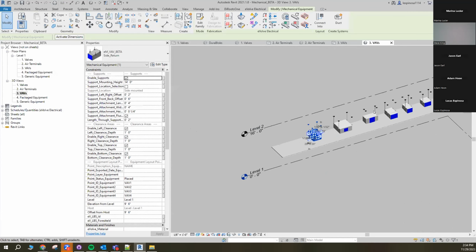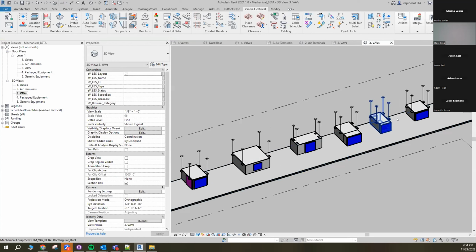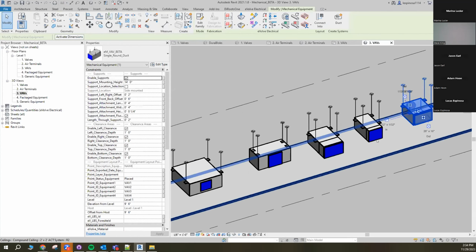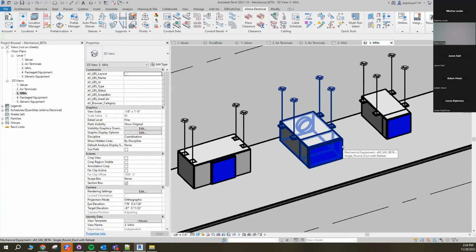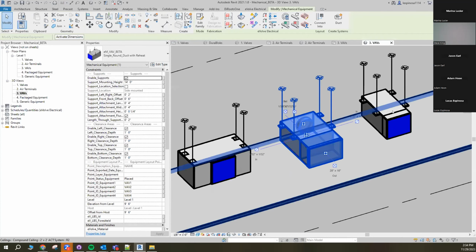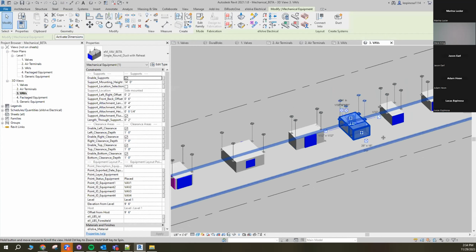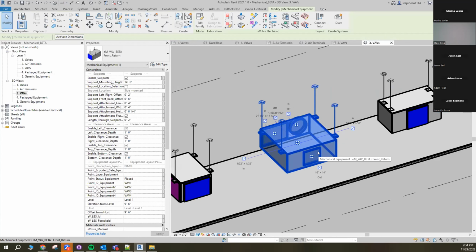Additionally, on the outlet side, we have the option to have that outlet match the box size, effectively being a plenum that we're just connecting to with some duct. In these couple configurations here, we have a reheat coil with differing lengths to it. In this configuration here, our outlet does not match the box size, it's just a centered small piece that's on the back there. We could also offset that left, right, up, and down.